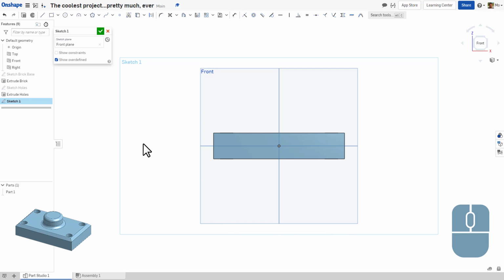And now, what is the shape that we need to draw? Yes, a rectangle. I'm going to choose a corner rectangle this time because I want to show you something. If I hover directly above the origin, not having clicked anything yet, you'll notice that there's this orange dotted line and this tiny little white box with a black vertical line in it.